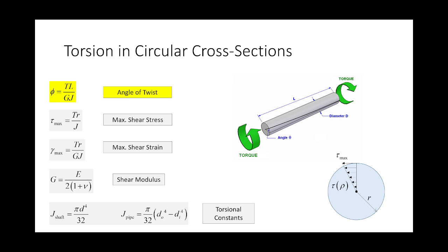For those of you that have had me for steel design, we had a discussion about warping when we talked about beams. Because when you have a beam and the top of it is experiencing compression and the bottom of it is experiencing tension, things in compression like to buckle, it doesn't know what to do. So it sort of kicks out and twists, and it undergoes this lateral torsional buckling mode, okay? Well, if you go into the governing equations governing that torsion, you find expressions related to warping, because that's where I-beams get their torsional strength, is from that warping effect. Under the pure torsion, they're incredibly weak, okay?